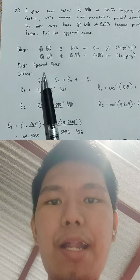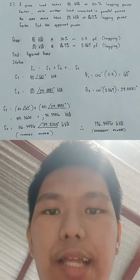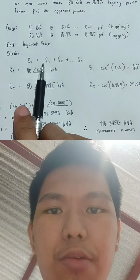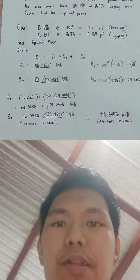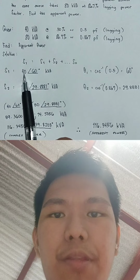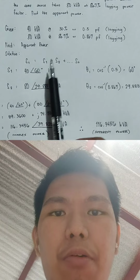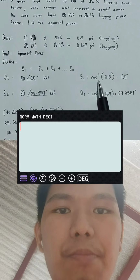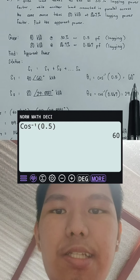Now, we will find the apparent power. The solution is the same as in number 1. The total complex power is equal to S1 plus S2 and so on. Since we have the two given, S1 is equal to 40 for its real part. To get the angle, we will use the power factor in decimal using this formula: theta equals cos raised to negative 1 of 0.5, which is equal to 60 degrees.